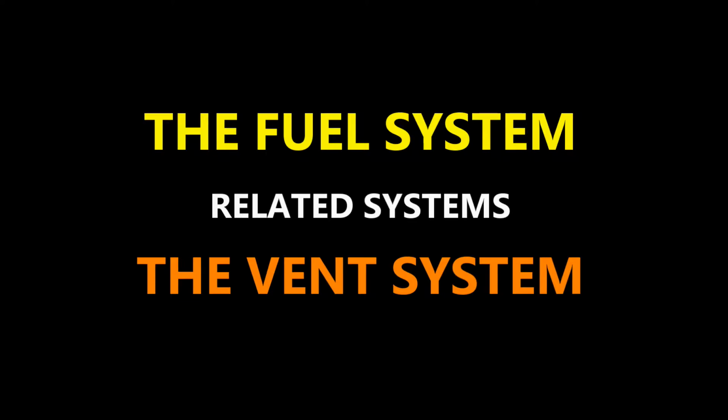Okay, so those are your wing tanks. I'm talking about the vent surge tanks there. Now, with the center tank, it's an external venting system that we have, where the fuel gas that comes out of the center tank is actually externally vented to make sure that it doesn't go into the aircraft structure. Just by the nature of where this is located, it's there. You're talking about fuel vapor, right? So all that can be ventilated.